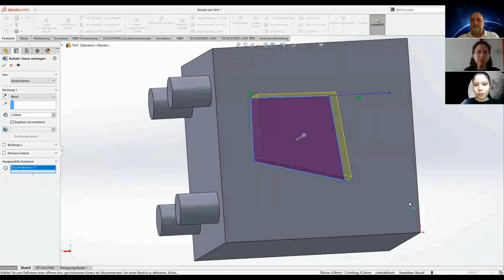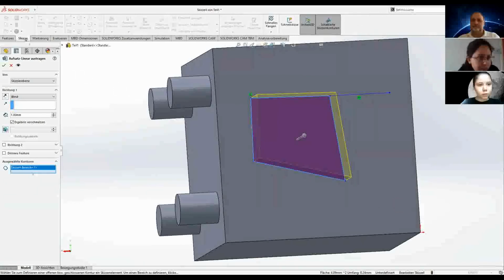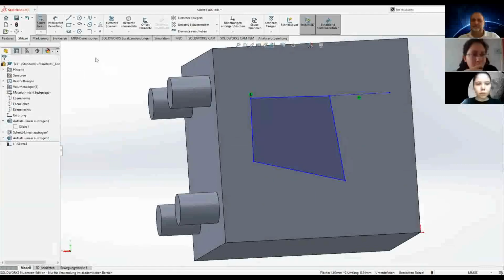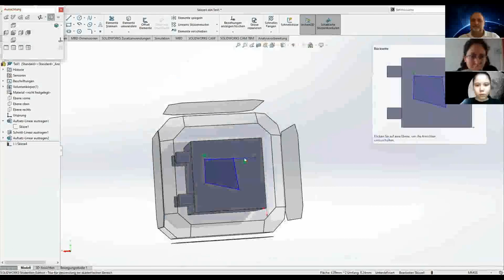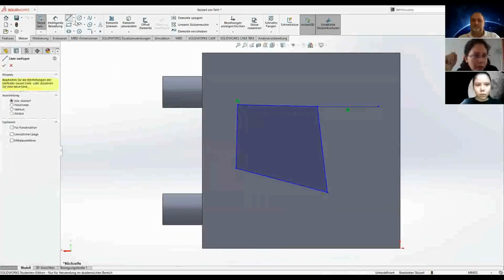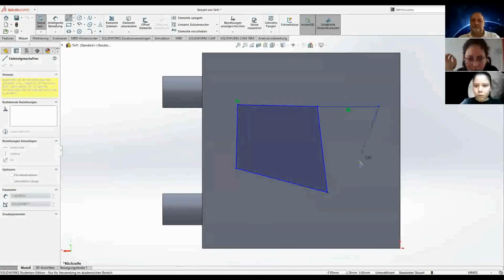So when you are building your lines, can you return to the sketch menu? Can you build a new line starting, yes, approaching one of the points that you already have, and you see that the point gets orange. It's really important that it gets orange, so you know that it's really touching. If you get a little bit below, now you are really close, but they are not touching. So can you start your line a little bit below to see what happens? Yes, like this. And you can also get to the other point, really close.